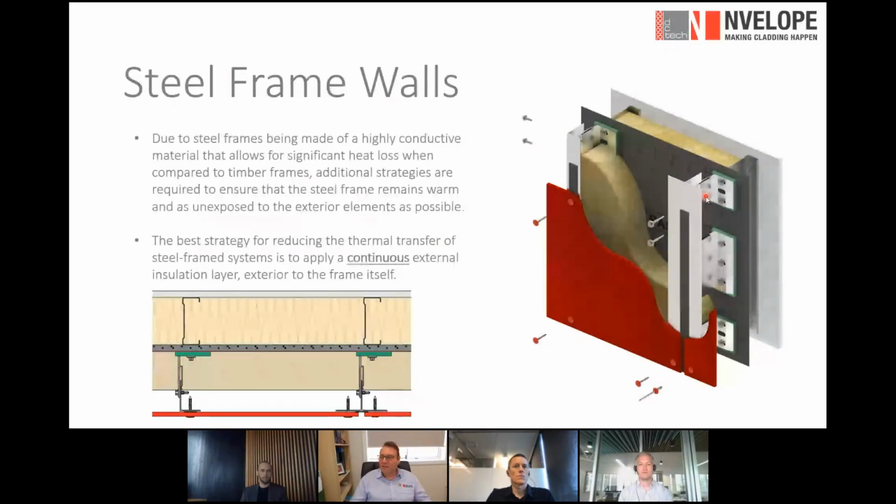What it also does is cantilever the cladding zone outward from the insulation, allowing for a strong mechanical connection back through to the substrate. So we're using the insulation to do its job, and that is just to insulate. It also creates a ventilated cavity, which deals with condensation. In addition to this, what we try to tell people to avoid is using the insulation as a structural component.